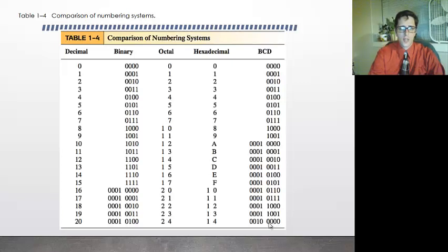It's kind of like if you think of the number system with digits, this is the ones digit, this is the tens, and so essentially what you're doing is creating that with the 4 bits. So we have 1, 2, 3, 4. That is representing a 0. 1, 2, 3, 4. That's representing a 2. So that's what we're representing with the BCD numbers.